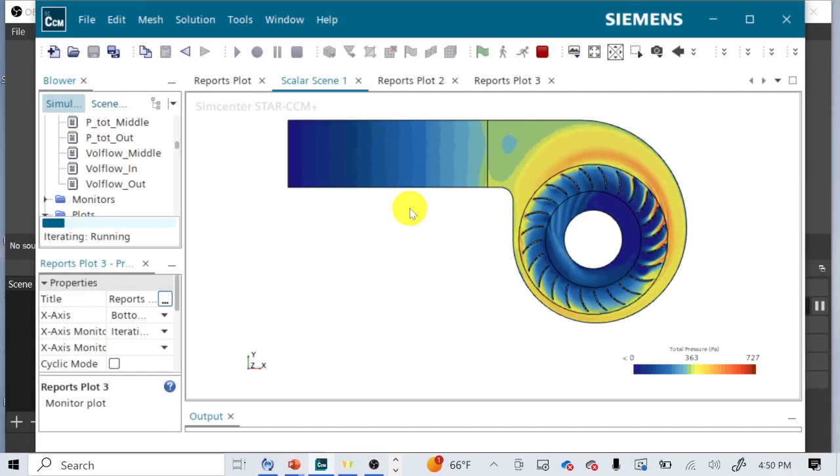That'll take a second to warm up. But we know that the total pressure came in at effectively 0. That was our inlet condition, right? That's a number we gave it. It shouldn't be anything other than a total pressure of 0 as it comes in. When it leaves, it's going to leave with some amount of total pressure. But when it exits the fan itself, it's going to have some different total pressure.